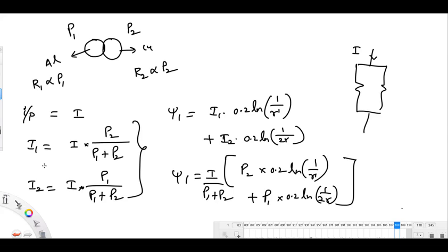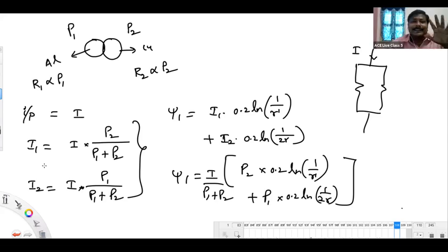Reactive power will always flow in the transmission line, sir. See, once you place a line or a winding, definitely L and C will exist. Yes or no? Yes. If L and C are existing, you can't avoid the storage and discharge of energy.